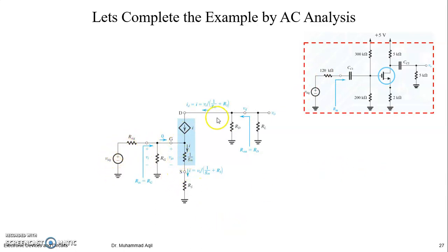And this equivalent model based circuit of this amplifier is not completed until we compute the newly introduced parameters, which are gm and 1 by gm: gm for this current source and 1 by gm for this T model resistance. So gm is ID over 2 VOV. When we put these values, we got this. 1 upon gm would be 1.2 kilo ohm.